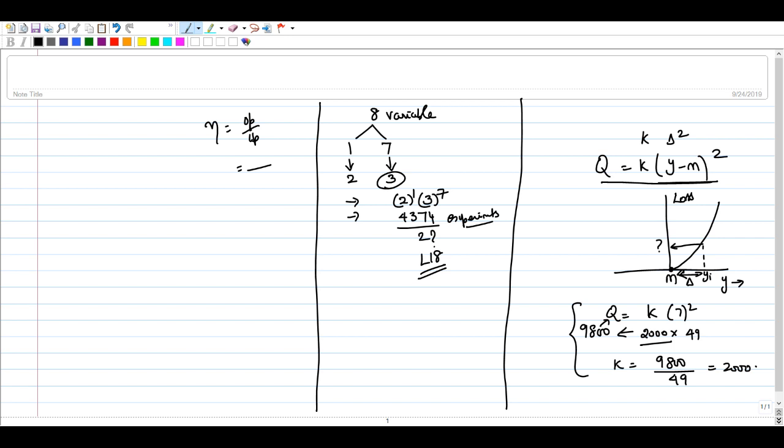For instance, we know that the fastener, any type of screw, is a different part, but that does not qualify as a theoretical minimum number of part, because the material, which is the second property, will be violated. It means that for its proper purpose, the screw could be of any material, so it could be of the same material as the part itself.